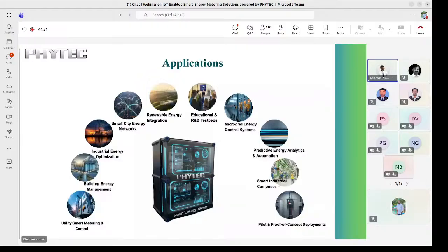Once the meter has the data, someone has to find out what the data is, meaning how to generate the bill, how much energy you consumed. So now it goes to the data exchange protocol. Here, if you use an optical meter reader, it gets the data from this data exchange protocol. Once it receives the data, it understands that this month you consumed this much energy. Some factors are used for calculating the bill, such as multiplying factors, and if reactive power is generated, a reactive power penalty factor also applies. Accordingly they generate the bill: per unit, according to the state, the price they set gives you the billing cost. Once you get the bill, you have to pay. That is the data exchange protocol. You read the data from the optical meter reader.